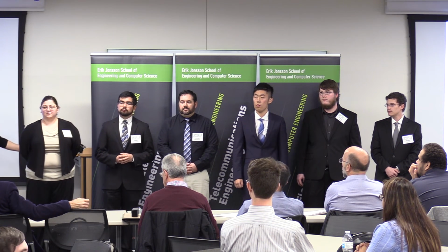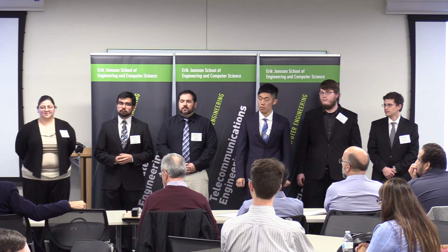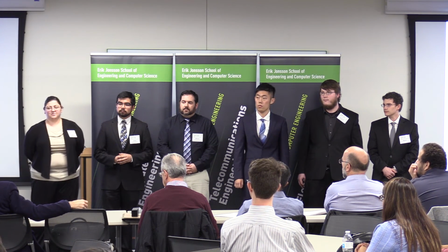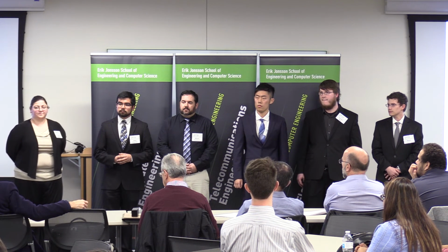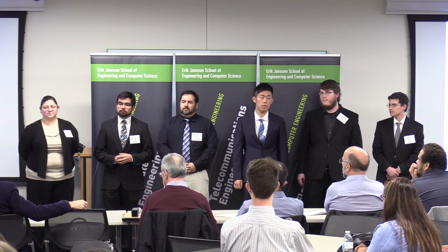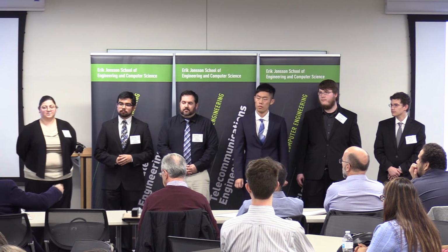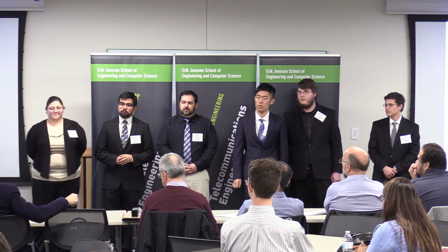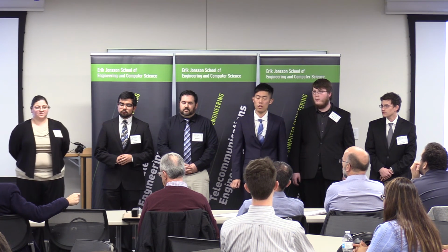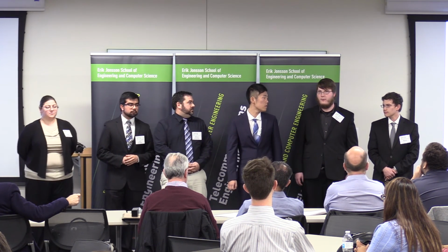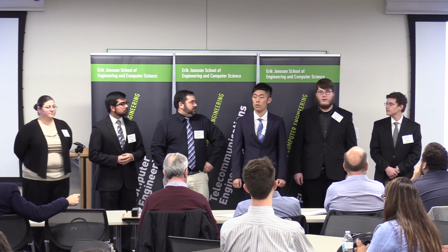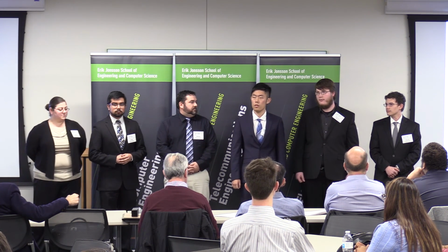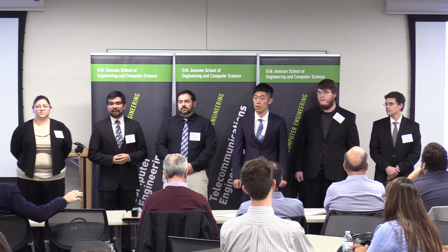And how can you do your experiments and development at 142 megahertz and then use that for a different band entirely? I mean, there's a very big difference between 2 to 30 megahertz and 140. 142 megahertz is a 2-meter wavelength, right? And then this is a much greater wavelength. So one of the reasons why we had to pick a higher frequency is because of size restrictions. Okay, so the whole project can still be scaled.